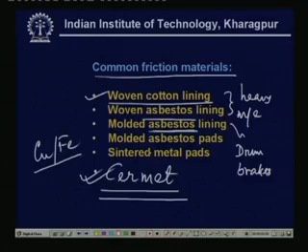Now, we come to the conclusions of these two lectures. We have studied different kinds of brakes. Now, the most important thing of the brake is the friction material. The friction material has to be chosen such that it is able to withstand high temperature, and it is not susceptible to wear and tear so frequently. The characteristics of friction materials are again found in the design handbook. Normally a few things are specified, the maximum pressure which could be withstood or the maximum temperature of the friction material.